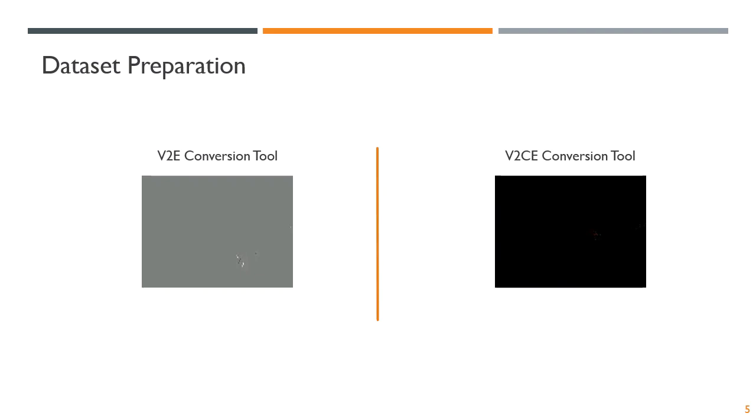Here we shall see the dataset preparation process. In a traditional frame-based sensor, the whole sensor array is triggered at a predefined frame rate, regardless of the actual speed. This leads to acquisition of large volumes of raw, undersampled data continuously. In a dynamic vision sensor, as shown here, each pixel activates itself depending on the intensity change it detects. This acquires only a small volume of essential motion information asynchronously.